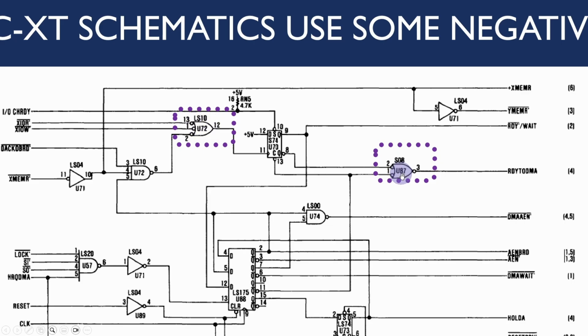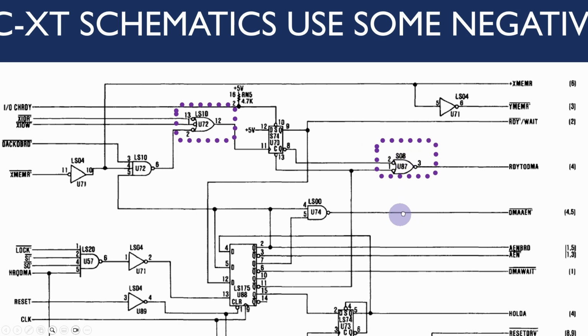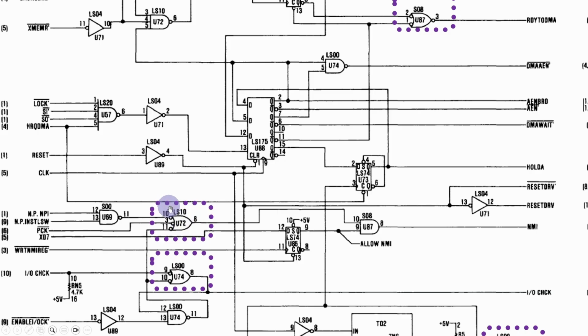And similarly here we have an OR type symbol, but because we've got the inverted on here and inverted on there, then in fact this is actually a 2-input AND gate. So the 08 was an AND gate in the earlier videos. And similarly down here we've got a 3-input one and a 2-input one. This one in particular is the NAND gate, so the LS00.